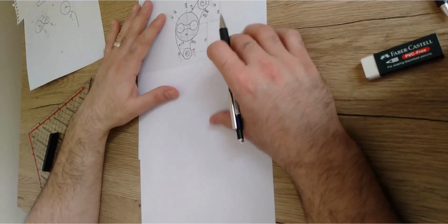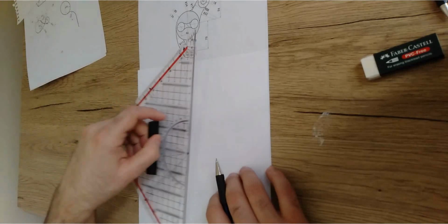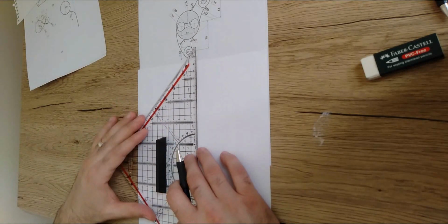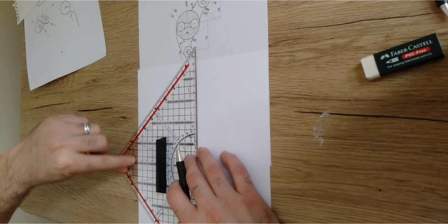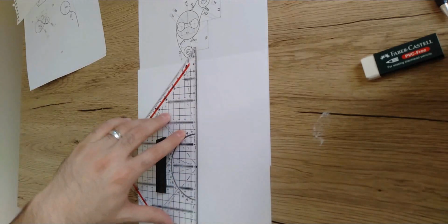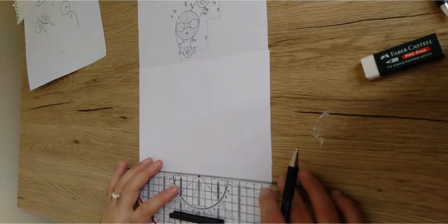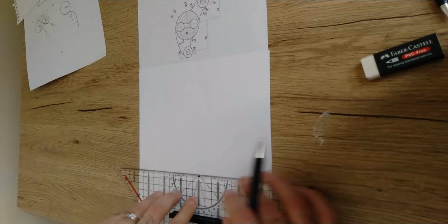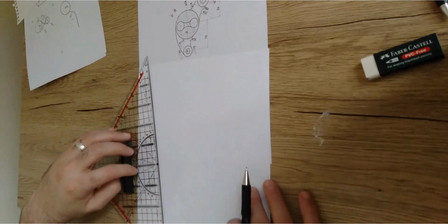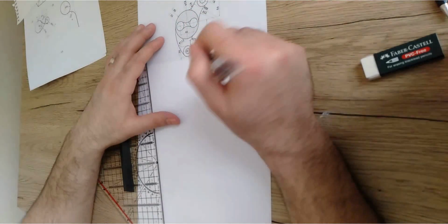so it would be enough for you to have the drawing, depending on the scale. So align the drawing sheet to be vertical, and as usual, just draw one vertical line, making sure that it is coinciding with the edge of the drawing sheet, and draw a very light line to be vertical. And I'm going to draw another horizontal line that is perpendicular to this one as two main reference lines, right? Then I'm just going to start from any point to be the center point of this big circle as just a start.